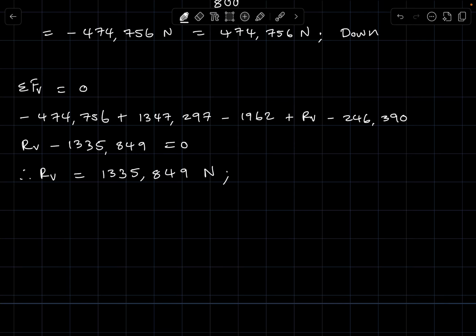It is positive, which means indeed it is headed up. We have determined LV as well as RV. That's the reactions at the bearing along the vertical plane.